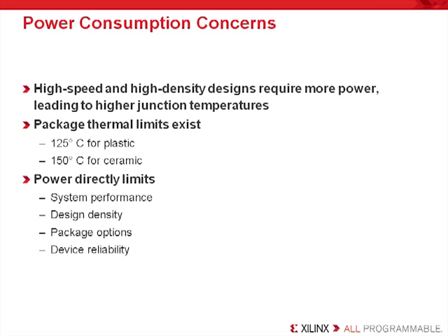To help you with this, you can use either the Xilinx Power Estimator spreadsheet or use the XPower Analyzer. The spreadsheet is the earliest possible form of power estimation, since it only requires you to have a rough estimate of your device utilization and an estimate of your activity rates. The XPower Analyzer will require you to have already built, synthesized, and implemented your design for power estimation to occur. But the XPower Analyzer estimate will be a more accurate estimate than that available from the Estimator spreadsheet.